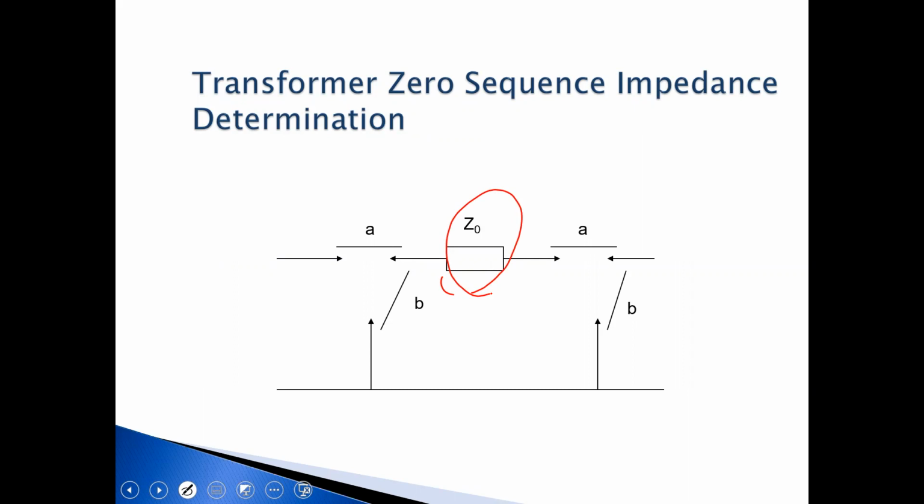If zero sequence can flow, meaning if I have a grounded star on that winding, then I'll close A. If I have a star, so if this is a grounded star delta, then I would close B. So in other words, for the zero sequence impedance, you wouldn't have any connection to ground, and then you'll have that. So that's what the connection would look like.